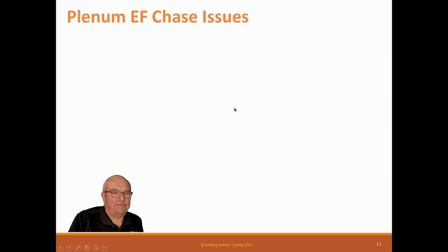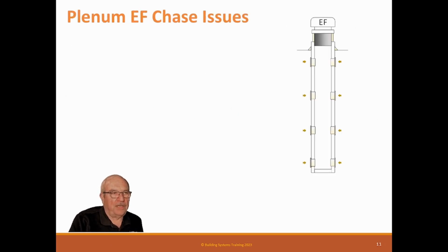down on the food. Here's another special case that you have to be aware of, and that is plenum exhaust. Sometimes designers, particularly architects, will design a system that has a vertical chase, and it's made out of sheetrock. And they'll want these small 50 CFM exhaust grills for a residential thing, like an apartment building or something. And they'll put an exhaust fan up here at the top, and they'll say, yeah, we just turn the fan on, and all this 50 CFMs will come out of these grills.